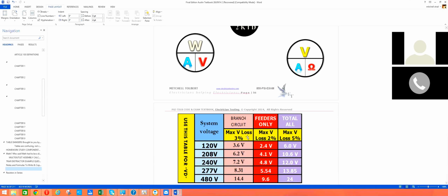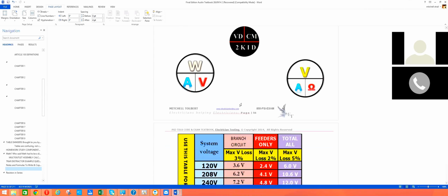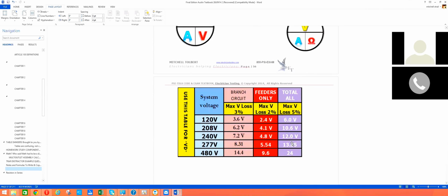So when you use these formulas up here, anytime you have to plug a number in for this VD on the bottom here if you're looking for wire size, or if you're looking for one of these bottom two values down here, either the maximum current or the maximum length or distance, if you have to plug some number in right here, it's going to be one of the numbers that you see on this table.